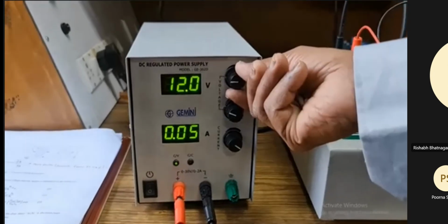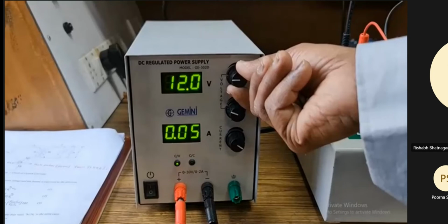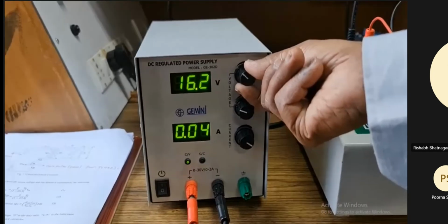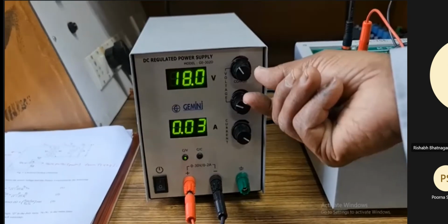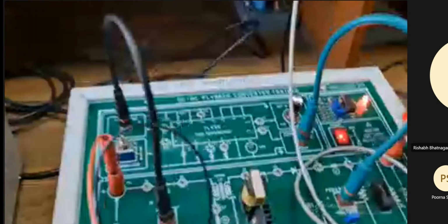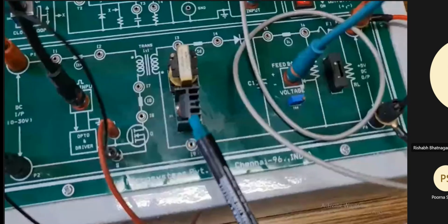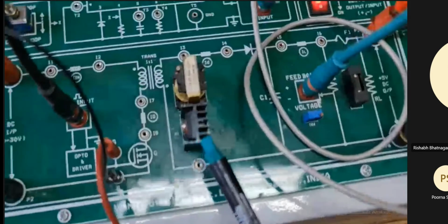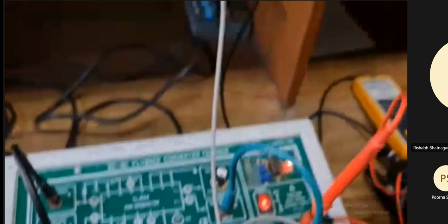Now the source voltage is changed from 12 to 18. So I am setting the source voltage to 18. When I change the supply voltage from 12 to 18, the closed loop operation of the converter, or control loop, is going to change the duty ratio which is driving this switch, from the 23% duty ratio which was the case.